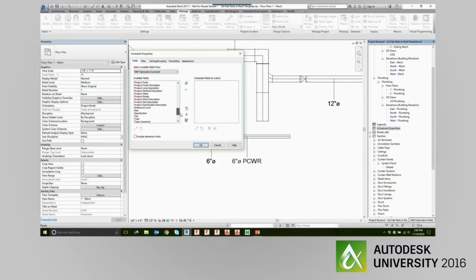A trick that I use to learn what fields report on what is pretty straightforward, probably not a huge secret. I'll just select everything using Shift and bring it over to the right-hand column as a learning tool. Your schedule probably wouldn't do you any good for any practical purpose other than finding out what information is there.